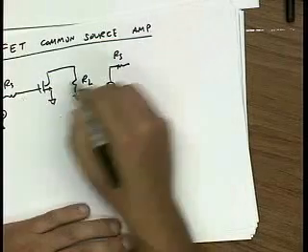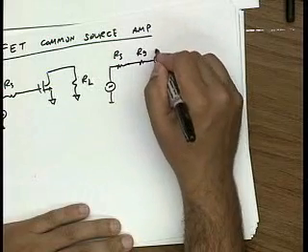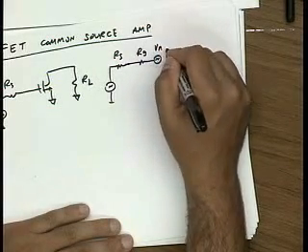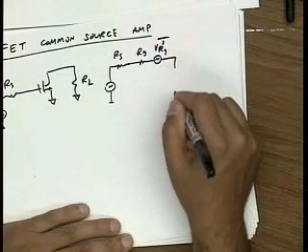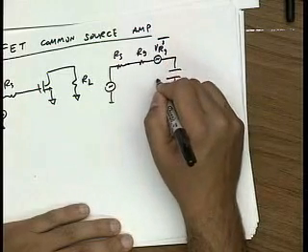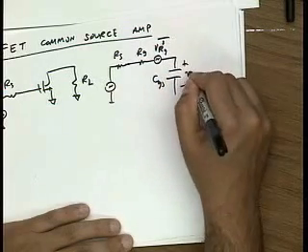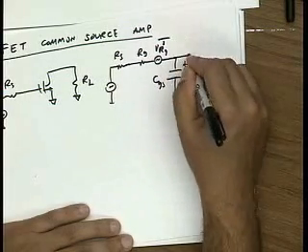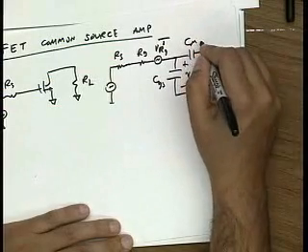The short way is you just draw the equivalent circuit with all the noise sources. So this is RS. We know the transistor has some gate resistance, and that's going to generate some noise, so let's call that VRG. Then we have basically Cin or CGS, VGS. We have C mu, or C gate to drain.